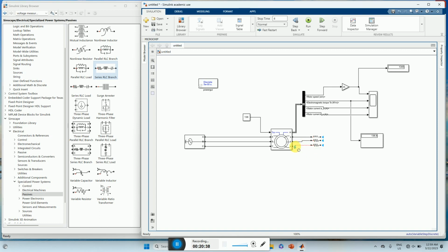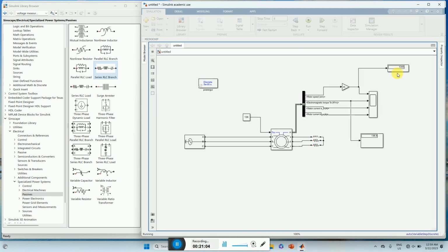Just like this. Oh, not connected. Yes. Sorry, we need to connect it. Connected. And the other side of this rotor resistance, we need to short it out. Correct. So when we add 10 ohm resistance, maybe it will not affect, but let us see. With 10 ohm resistance, 1345 was that. Oh, but we are getting a negative speed over here.